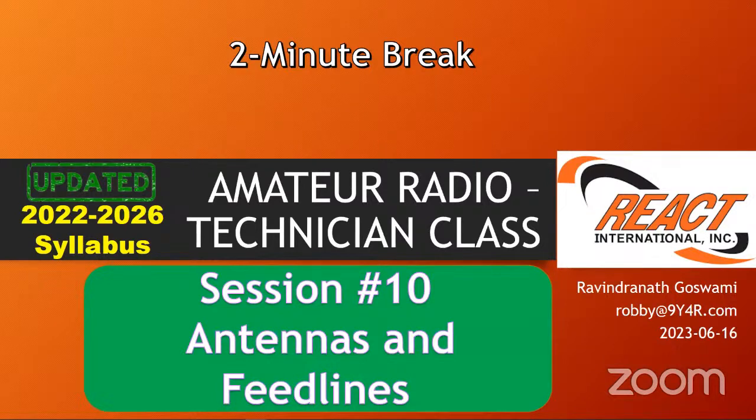All right. Yeah, good evening, Adish. Great to have you. So Norman asks, is there wattage that is recommended for SWR meter? I noticed the ranging from 100 watts to 300 watts. So I would answer that by saying just make sure that it covers the maximum transmitter power that you're going to connect it. That's my little rule of thumb.